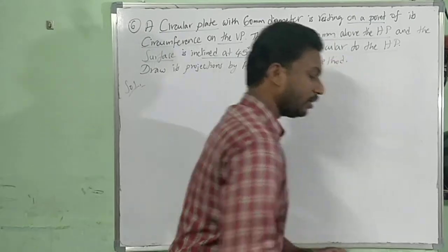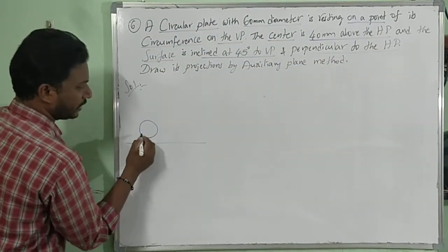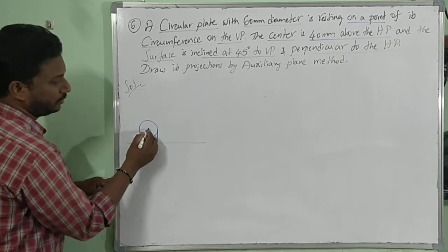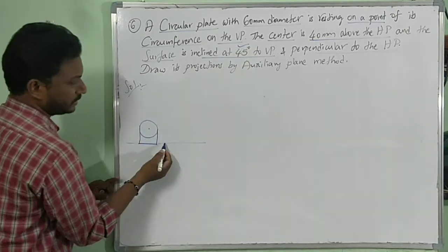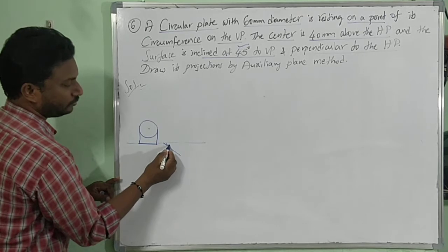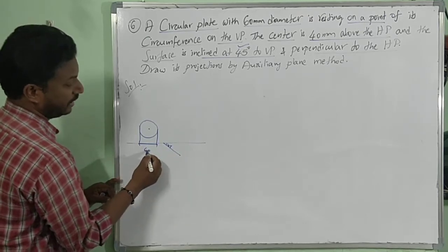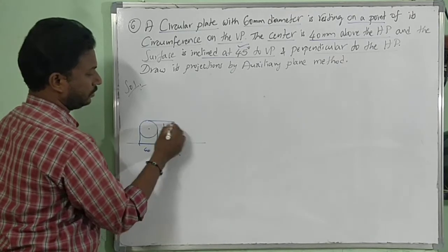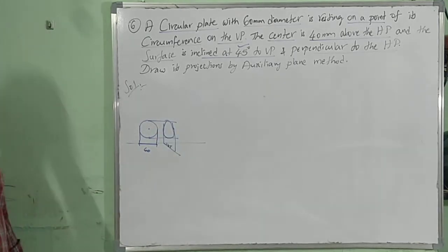See, the regular method I will also show you. It is also stage by stage. We will draw the front view circle and the top view straight line with the center. Now for this straight line with respect to 45 degrees, we will draw a line, of diameter 60. Now from here, it will be elliptical. Regular method, 2 stages.